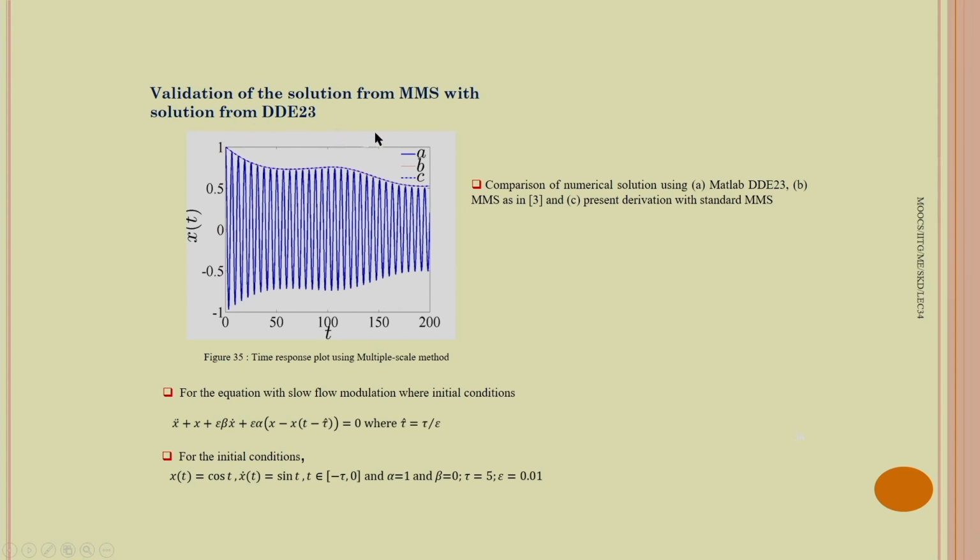The advantage of using the method of multiple scales is that in addition to getting the accurate time response, you can get the frequency and force response plot of the system, and the analysis can be extended to know the effects of different system parameters on the turning operation.